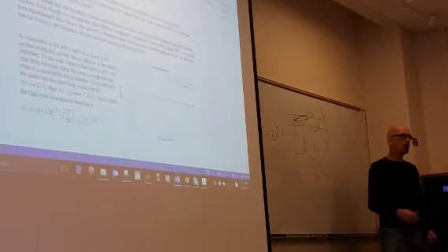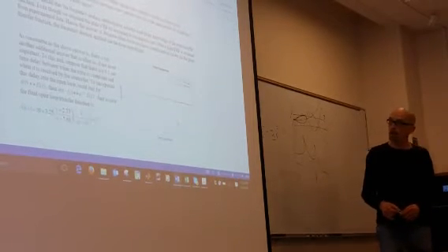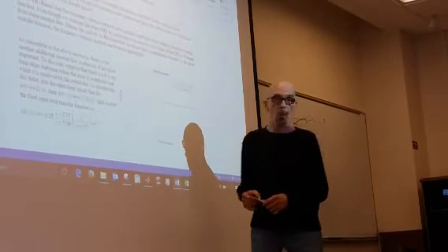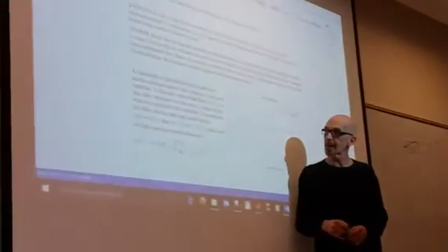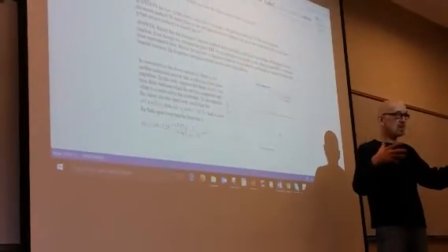You can do it directly in the frequency domain using a plant FRF, and test engineers get FRFs all the time. But there's another reason for this, and it's a more important reason for you guys, and I mentioned it last time. Suppose that there's a 0.1 second time delay between when the error is computed and when it's received by the controller. Now, 1/10 of a second can be a long time. It could be that the controller, the error is being sent via Bluetooth or some channel, but it could also be that it's all wired into the same unit.